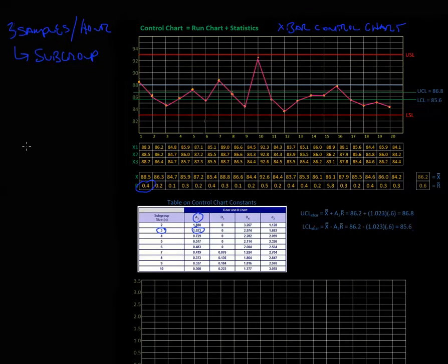We mentioned that we were doing a heat treating process. Maybe we're doing an annealing process. Well, the annealing process itself might be consistent, but the material we're bringing into it may not be. So there may be different chemistries within the steel grades. It's just an example that's causing the parts themselves to respond differently to the heat treating process.